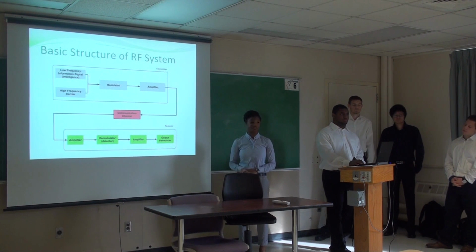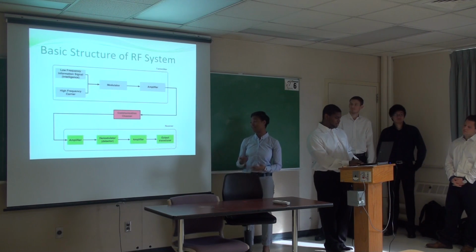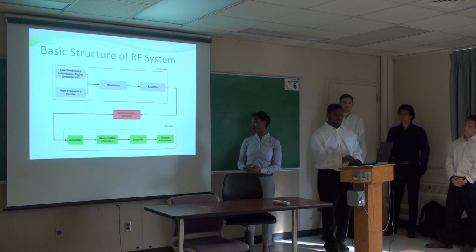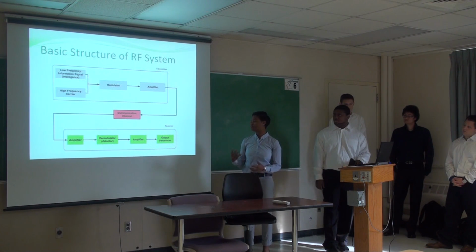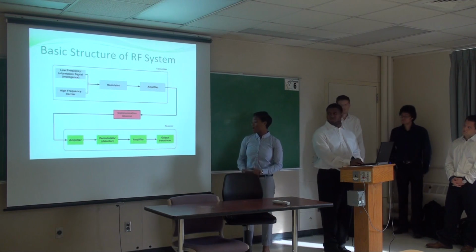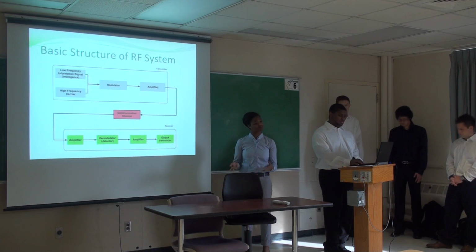to the receiver. And the receiver is comprised of an amplifier to amplify the signal that it received, a demodulator, and some sort of output so that you can see the signal or receive the signal and take it and put it somewhere. They also have, it's not actually in this diagram, a tuner, and a tuner is